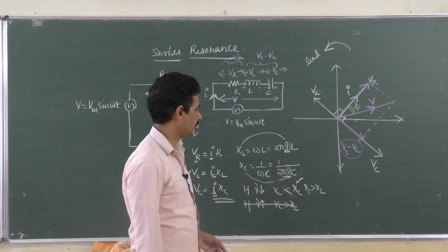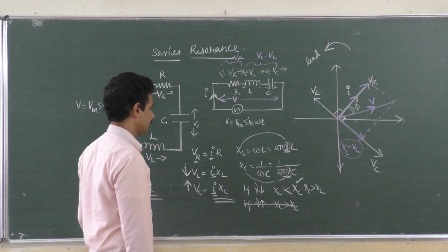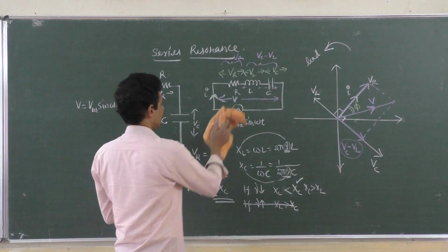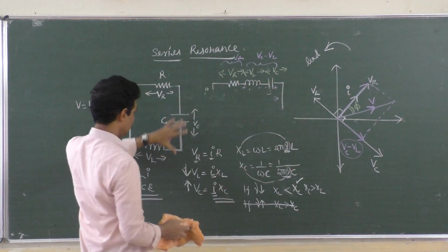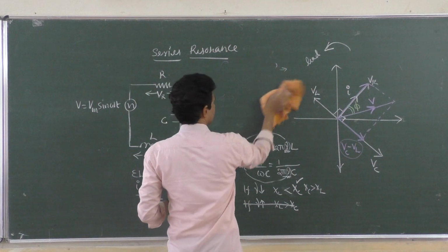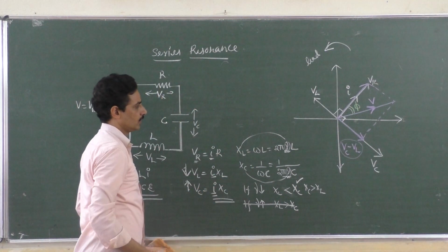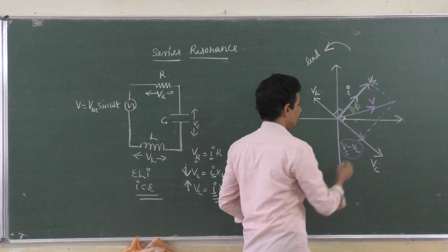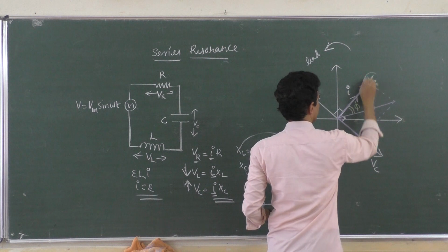Now find out what V is. Apply that parallelogram law of vector addition. So where should I write now? Shall I write here, on this one? Because I have here this diagram we have to follow in the exam. The final voltage can be easily found out now. So you know that this is VR and this is VC minus VL. These are the two things which you have to consider now.